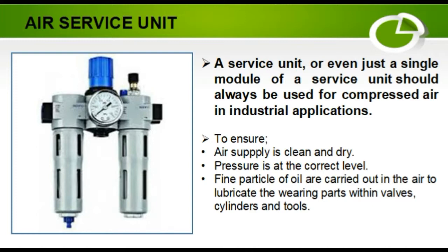Why is the air service unit important? The first reason is to ensure the air supply is clean and dry. The second is to ensure the pressure is at the correct level. And the third is that fine particles of oil are carried in the air to lubricate the wearing parts within valves, cylinders and tools.